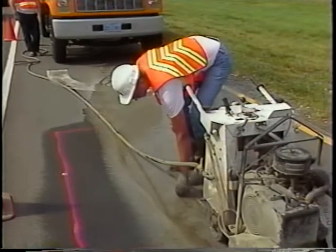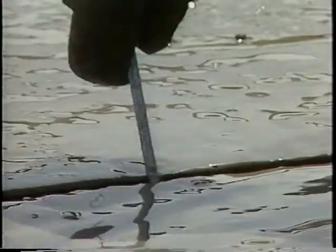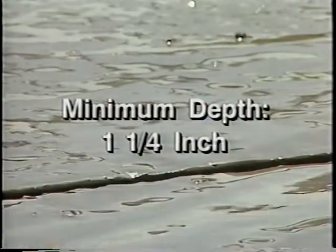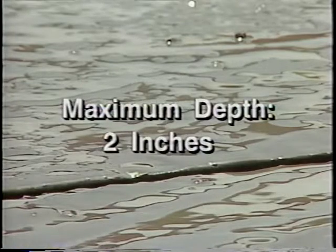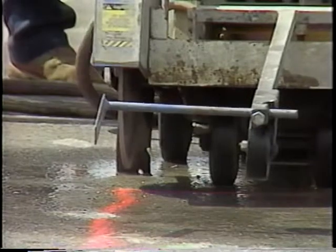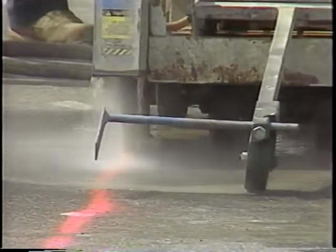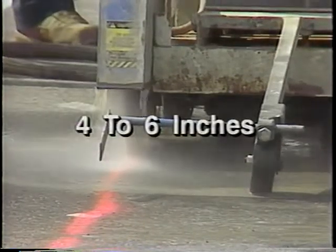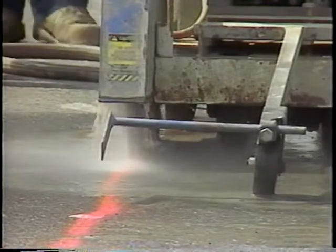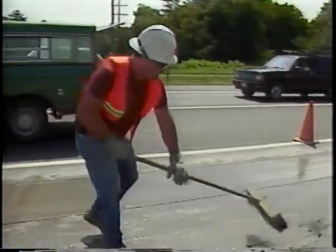Check the depth of the saw cut frequently to assure that it is constant. Although the appropriate depth depends on the number of turns of wire, a minimum depth of 1 1/4 inch and a maximum depth of 2 inches should be maintained. If your saw cut is out of alignment, do not make a second cut near the first. If a second slot is necessary, cut at least 4 to 6 inches from the original slot to avoid significantly weakening the pavement.